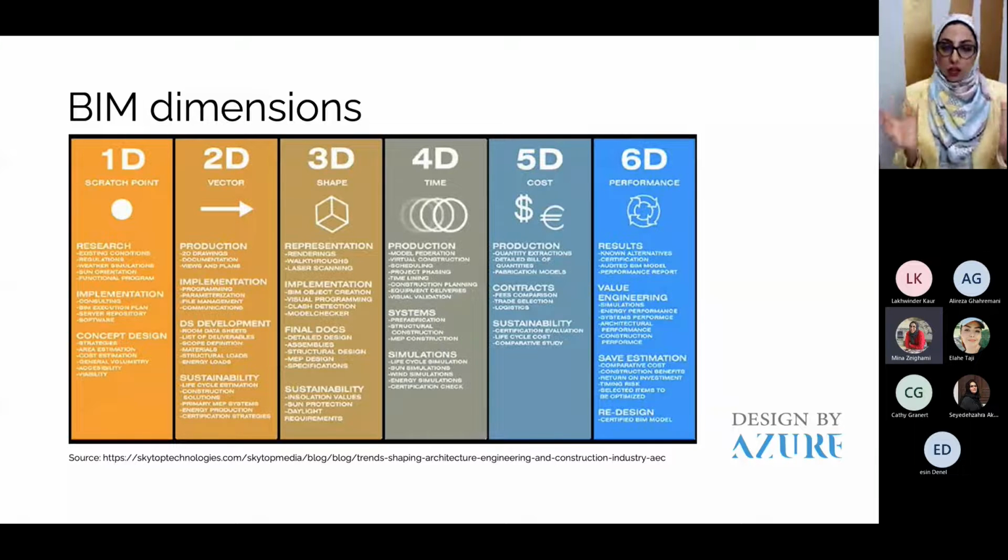Like you create AutoCAD drawings for programming the projects better. But then you take the 2D drawings into 3D drawings and create renderings, walkthrough of the space, and use laser scanning, which is a BIM device to scan the building, and also clash detection before you even start the construction on the job site. You can compare different disciplines together and figure out what the clashes are in the process, so you can plan that ahead of the construction.